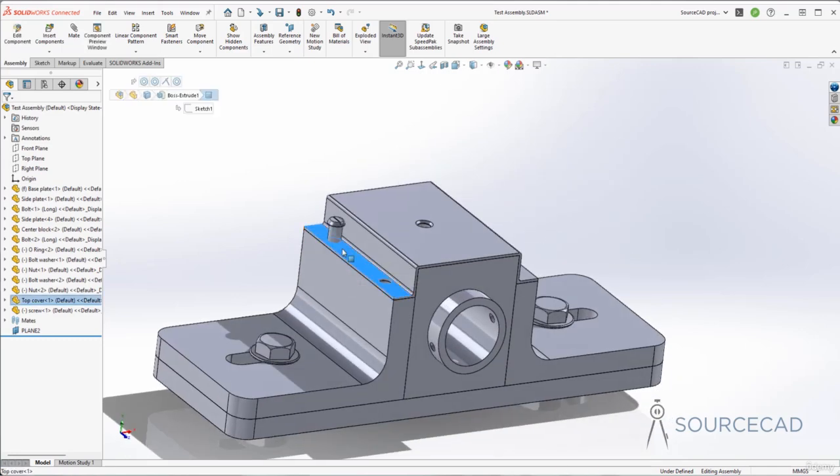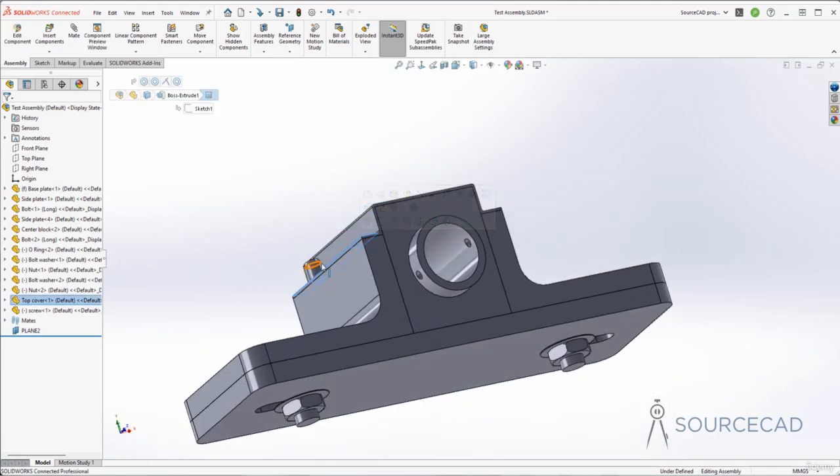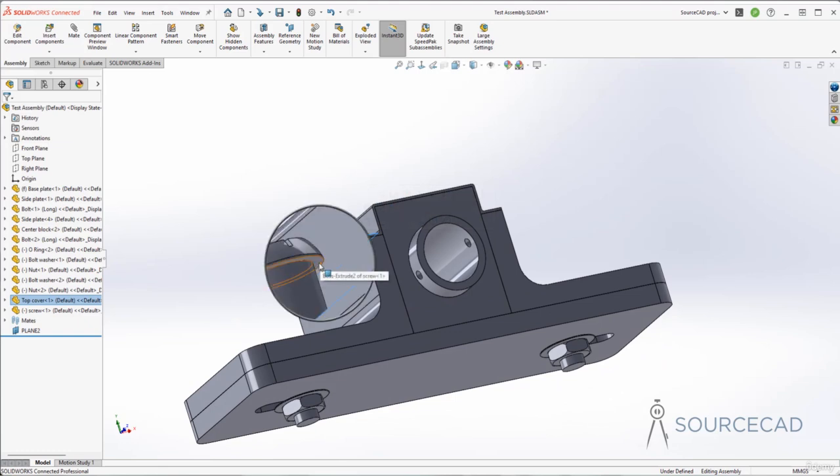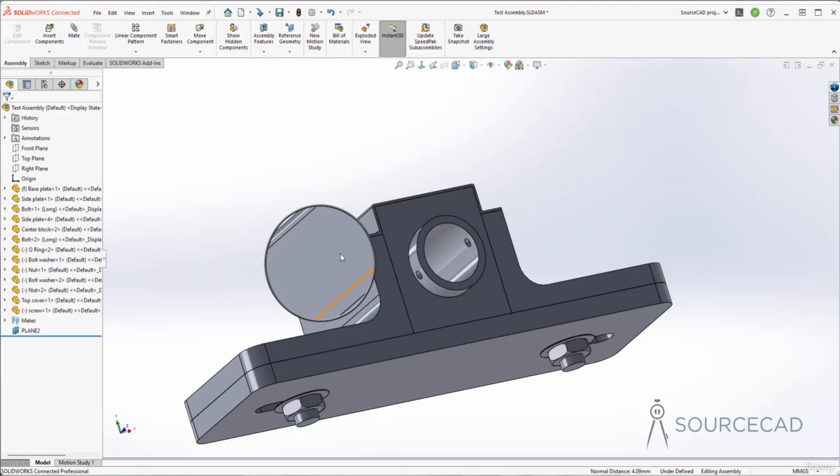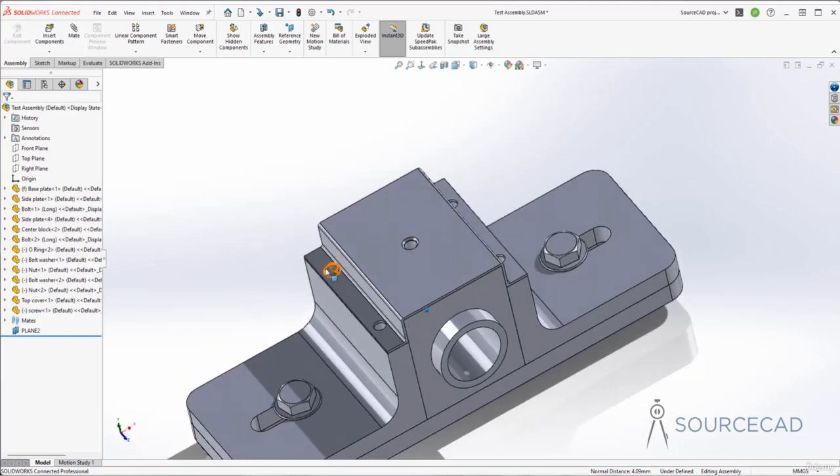So I'll just select this one, then I'll orbit this, and once again I'll type G and control and click. Now this should be coincident and done. Press escape and we have it right in place. All right, so we've added this screw very easily.